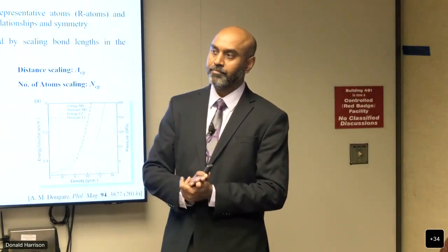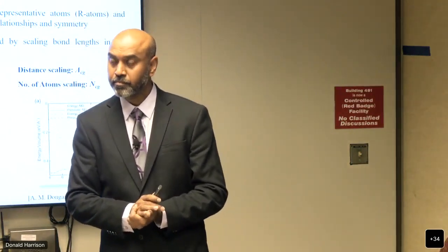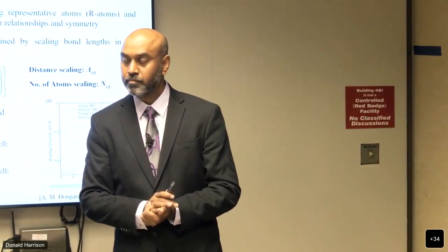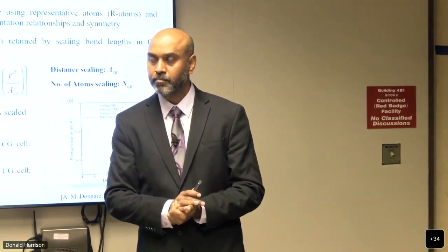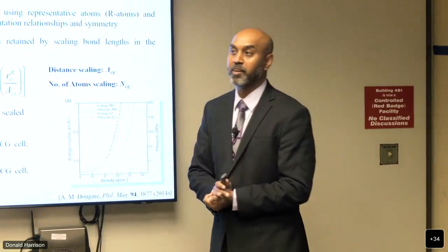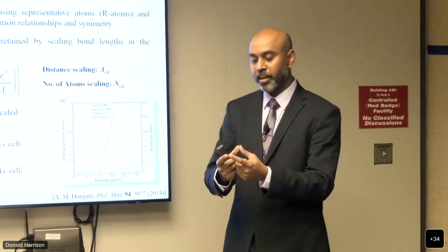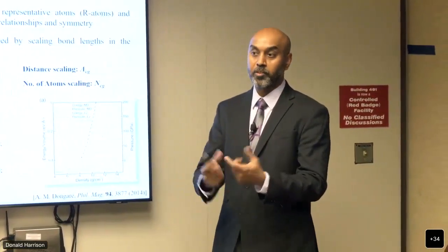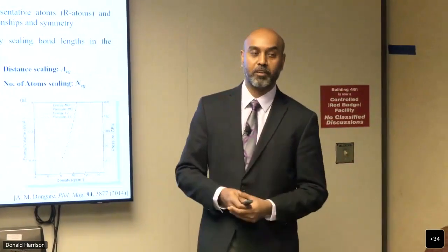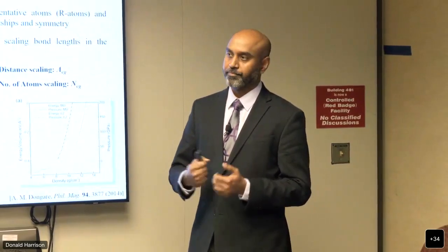And there's also a question from Saranj, who says, what is the orientation resolution of the template matching method? Can it resolve the small changes in orientation within a single grain upon shock? Yes, we can. So anything where you can identify a cluster of atoms that are together, where they are not identified as disordered, where you see an orientation, we will capture that as well. So anything around the order of a few nanometers, we will see those things as well.